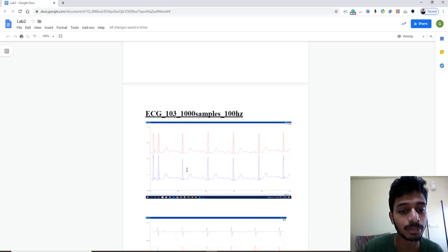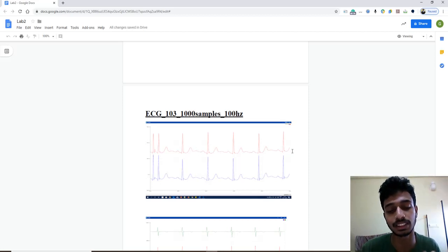What my order should be, I'll get to know through experience. Here we have tried various orders and found that order 3 works very well. It retains the spike as well as smoothens the signal. As you can see, there is a little noise component here which is smoothened, and every spike is retained. So there is a trade-off between smoothness and retaining of spikes, and we need to choose the best possible trade-off.